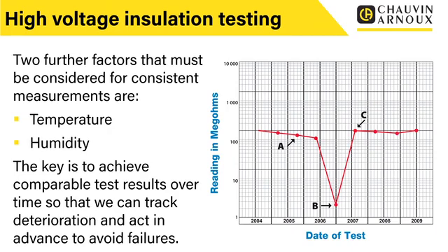And then we put it back into service, and we continue at point C to monitor that insulation resistance over time, ensuring that it stays within the parameters we'd expect and we haven't seen any deterioration. So by plotting insulation resistance over time, we can check what's going on with the condition of the insulation. But again, as we're taking these readings, as we said, we want a constant temperature.